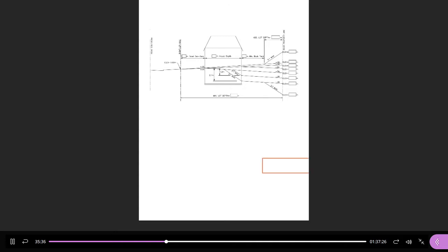So to figure out this number here, the lot depth, you simply go to the AutoCAD drawing and list the line between units. So I'm just going to tell you what I'm going to use for today's calculation, but certainly you want to get that. So that's where this number comes from. What's the distance from the corner at the front to the corner at the back, which is just the length of the side of the lot.